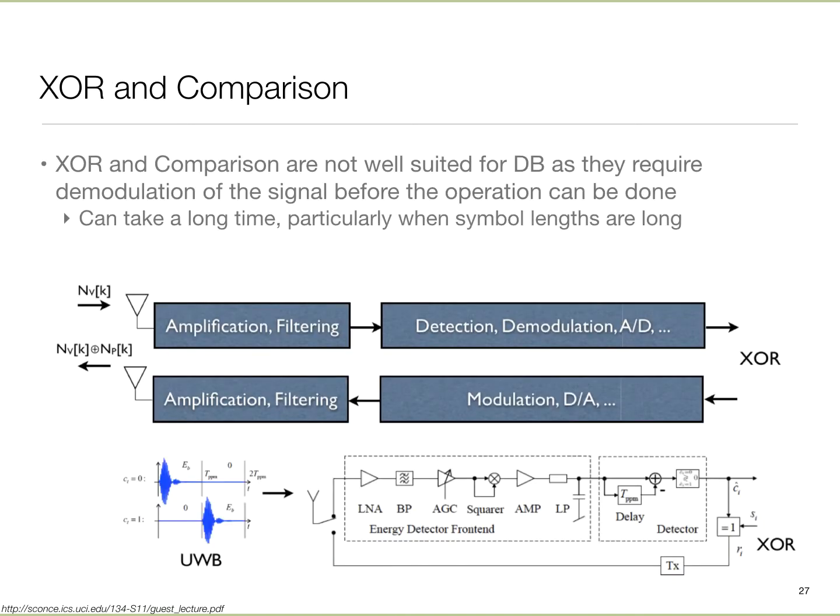The problem is, to do all of this, we still need to go through some circuitry on the receive side. The incoming radio signal over the antenna, you have to amplify it, you have to filter it, you have to detect the bits, go through demodulation, A to D conversion, and all, and eventually you have the bits. And then the processor does the hardware gate XOR operation, and then it goes out. All of this still has some delay in it, okay? Tiny as it may be.